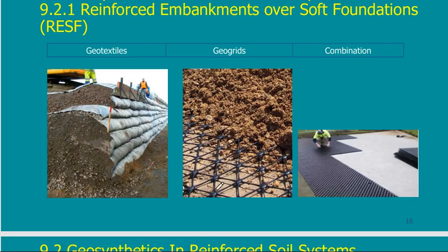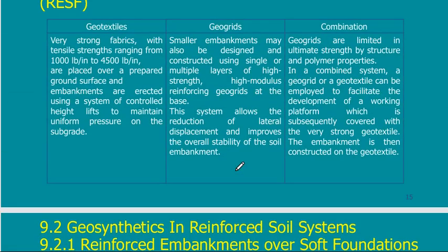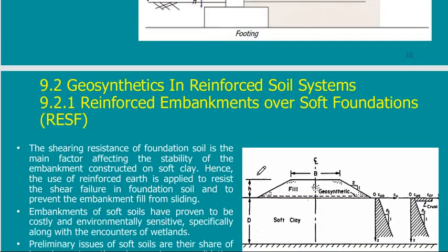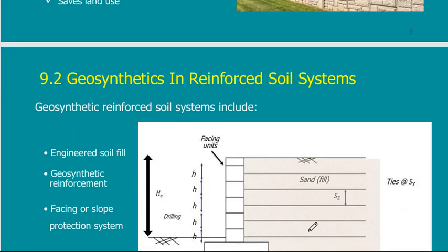But what I do with this layer of mesh here, once I reach here, this is the mesh here. I put this wire mesh. But once I reach the facing, I connect it with the facing. So at the start of the construction, I will put this piece, this facing only. And once I put this facing, I put this wire mesh.